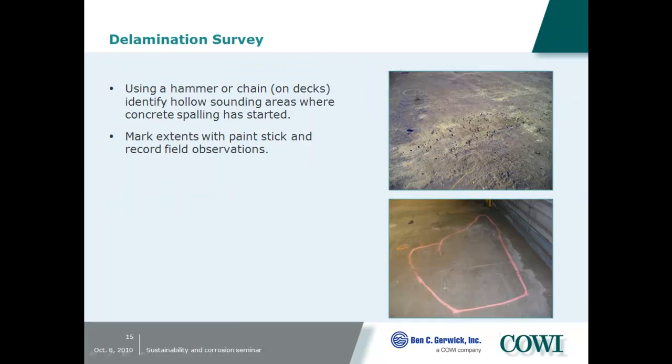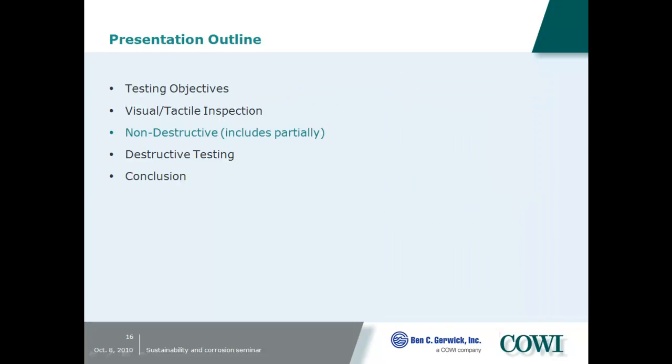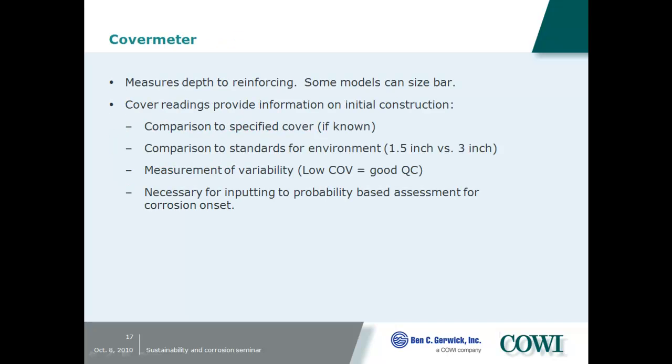And you can use hammers, or even chains on a deck if you don't have a membrane on top of it, and you limit where you have your direct deteriorations, very often corrosion. Non-destructive testing: the cover meter is a very simple tool to measure both the concrete cover depth and very often also the reinforcement diameter. So you can use it to compare to the as-built drawings. In some cases you cannot use cover meters if you have a very high steel density, very narrowly spaced reinforcement bars, then your cover meter will not be able to distinguish between them.